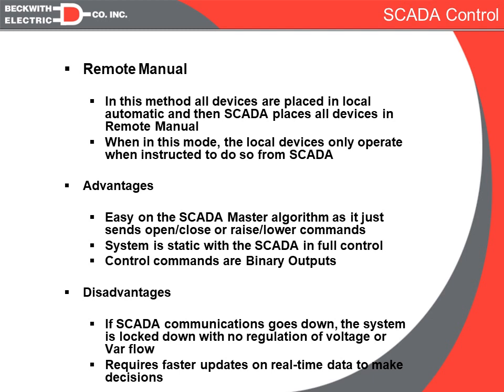Likewise, if you're a regulator or an LTC control, you're not looking at the voltage to determine if you need to raise a tap or lower a tap. You're waiting for SCADA to instruct you to raise a tap or lower a tap. The advantage of doing it this way is that it doesn't require as much processing on the SCADA Master, and the commands that are being sent out are digital output, or binary output commands, which don't take up that much bandwidth.